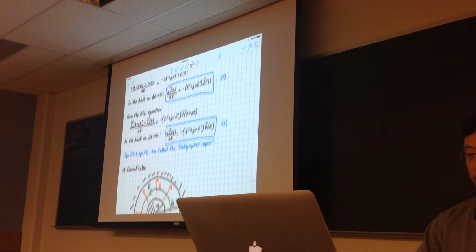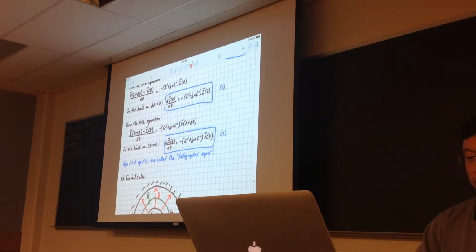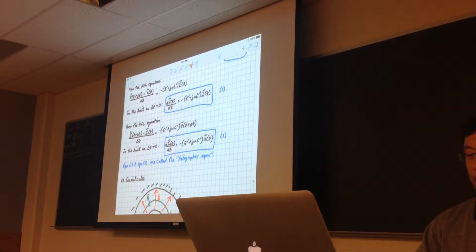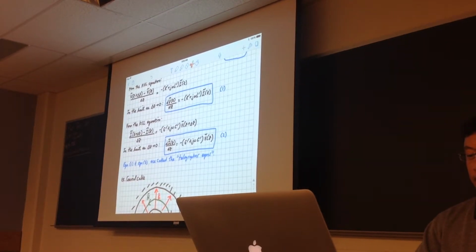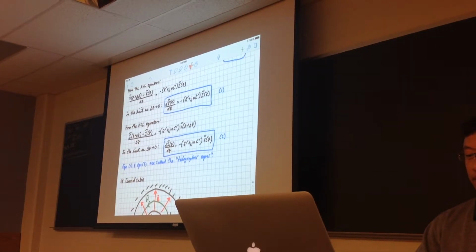We did a number of things. We took our telegrapher equations 1 and 2 from our transmission line model, and it's a first order ordinary differential equation system of solutions. These two equations are coupled because V and I appear in both. And if we were to look at this as a mathematical problem, we can solve for voltage or current by taking the derivative of one of the equations and plugging in the other.